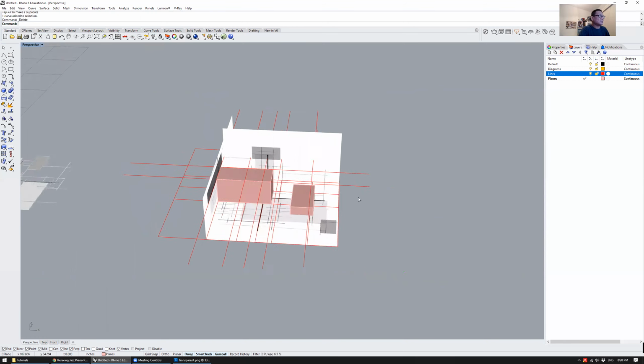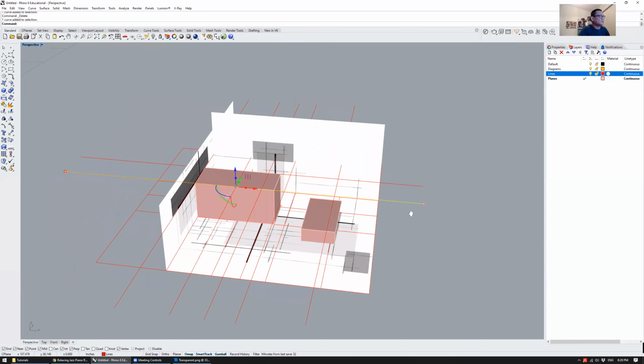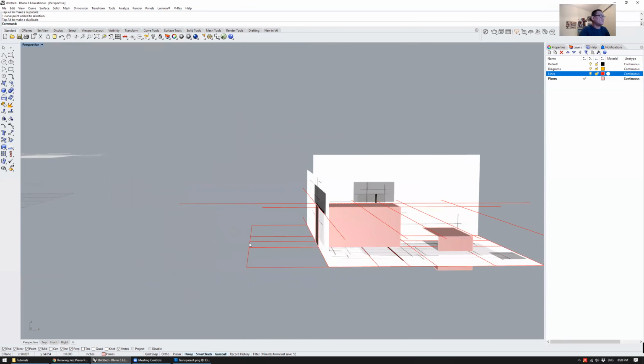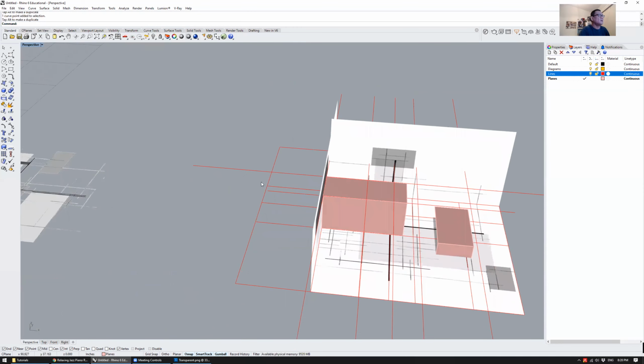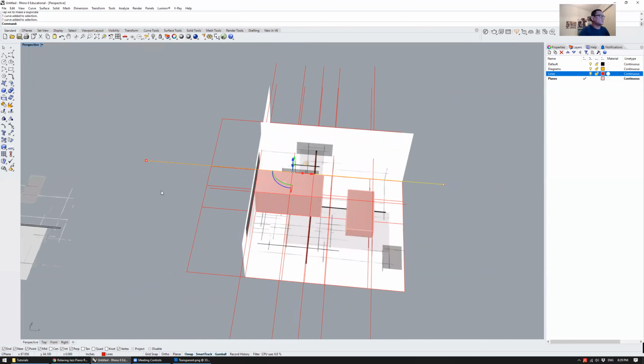But what that means is that if I want to change the length of these lines, I can click on this guy and just scoot it back. If I'm just eyeballing it, I can click on the end grips and scoot it back. The trim method works better if you're really trying to make sure it aligns perfectly with some other geometry. But if you're just editing to get it to do something, then that works as well.